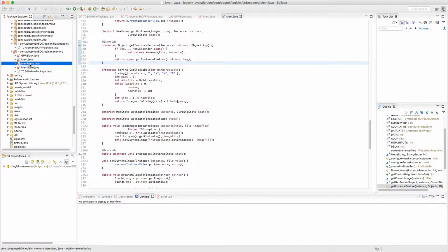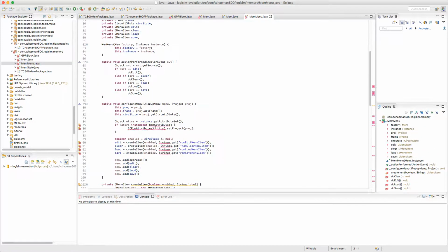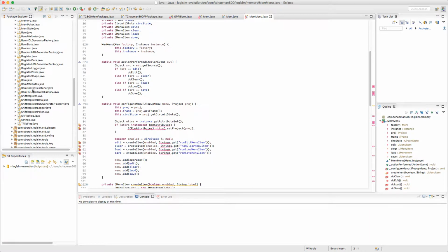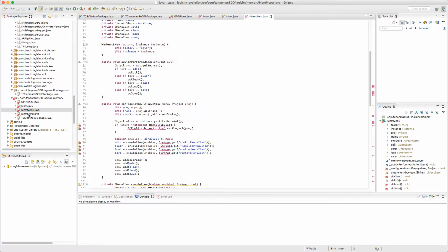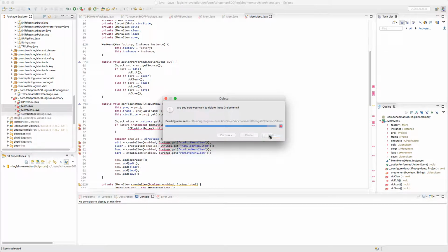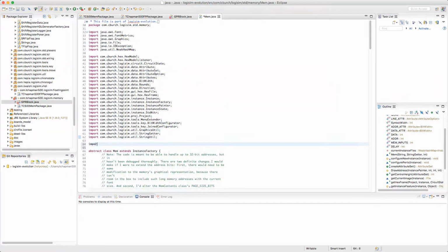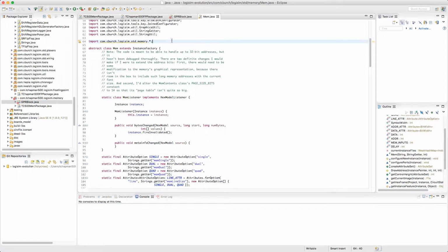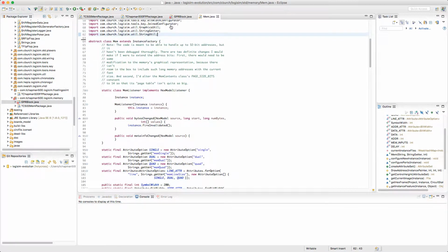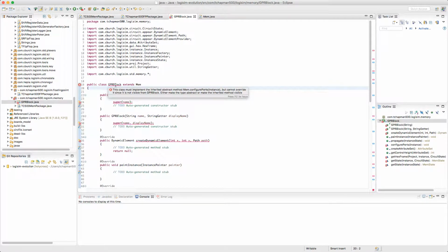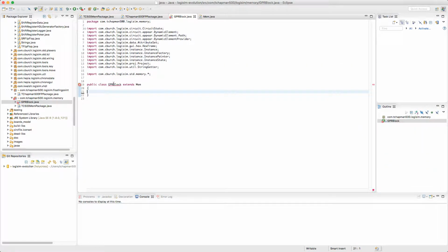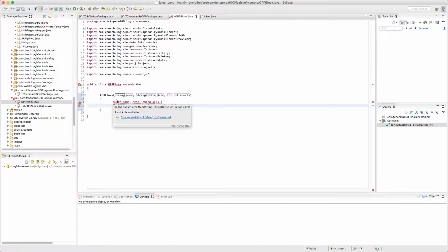Oh, that's annoying. Now, the actual implementation of this GPR block is just a set of registers that have been multiplexed together. Their inputs are multiplexed according to the address, and their outputs are multiplexed according to their address. The outputs and inputs are going to be to and from the bus, and also to and from the ALU. There are two different outputs, and there's going to be a special input bit that selects one or the other.